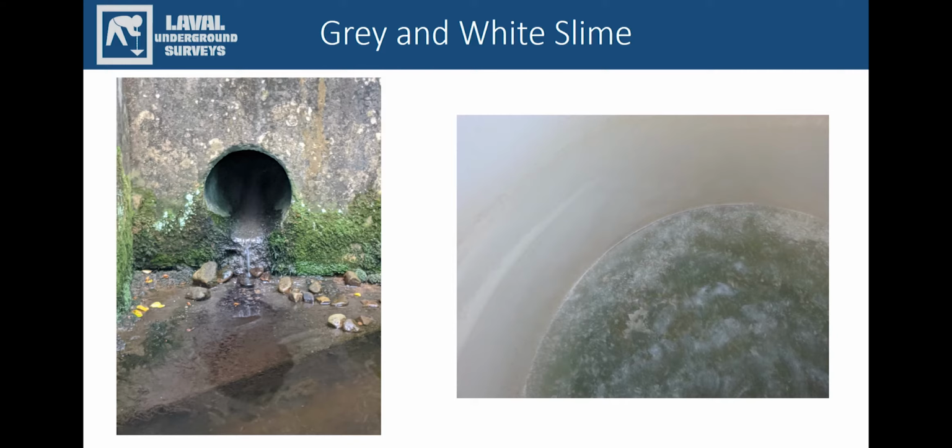Within the confines of biofouling, there are different types of slime. Close inspection of the slime reveals that gray and white slime will often consist of a white or a clear slime, within which there are intense black granules. Such black deposits are most commonly metallic sulfides, often iron and manganese, generated by interactions between the various metallic salts and hydrogen sulfide. This hydrogen sulfide may be generated by bacteria growing in the absence of oxygen and reducing sulfur, sulfate, or via protein degraders.